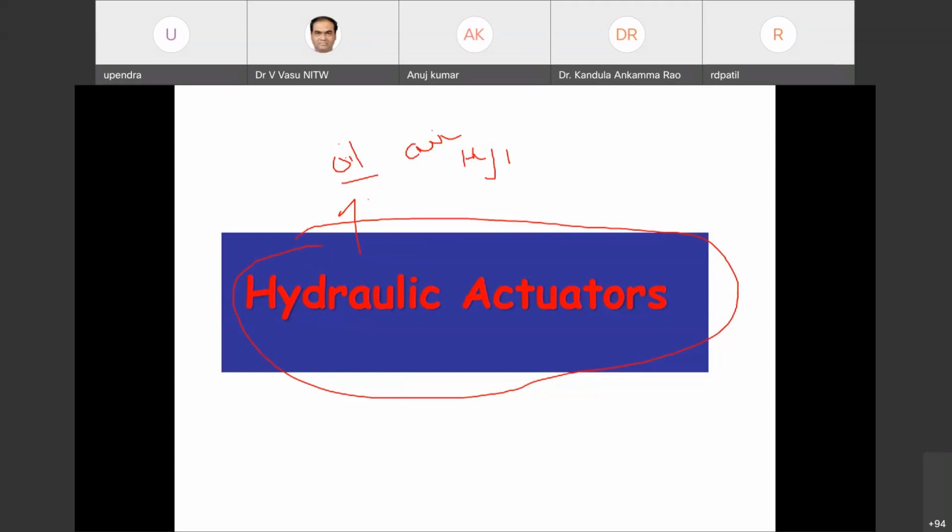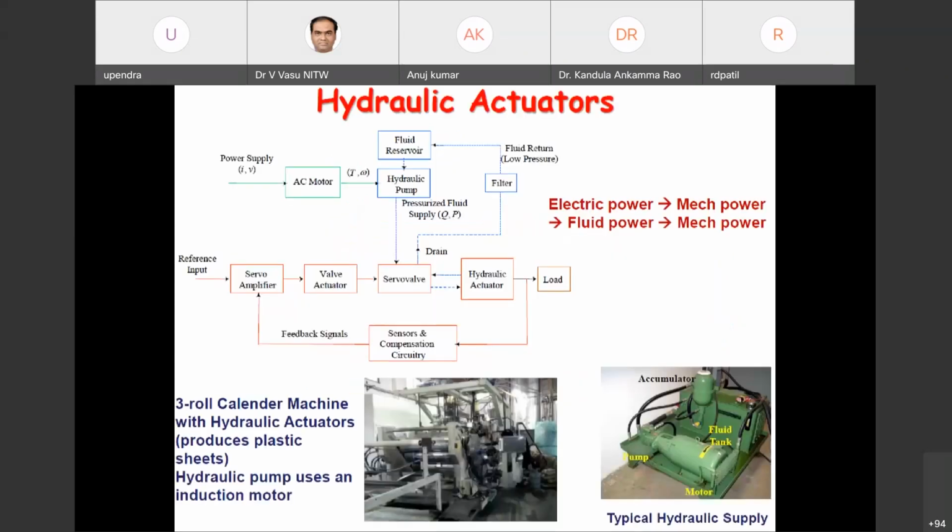Another important thing is that hydraulic actuators are used if you want higher loads and higher force. Suppose you are using JCBs, there hydraulic actuators are mainly used. When you need lesser forces, like opening the doors of a Volvo bus, then pneumatic actuators are mainly used.